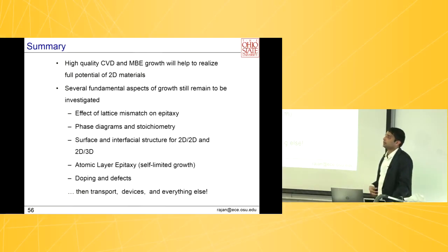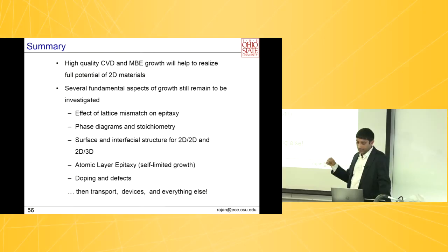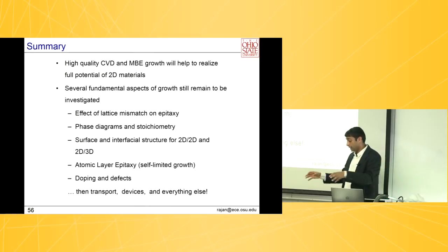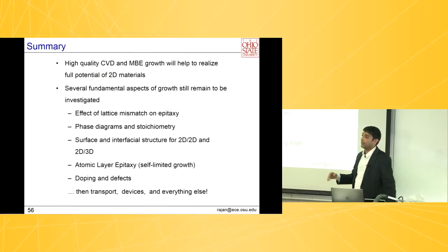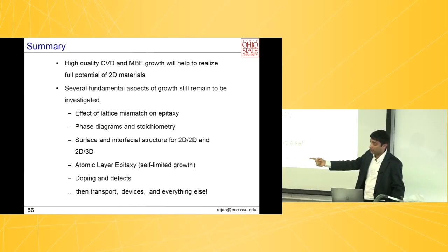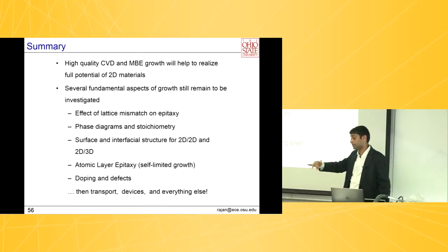What I was saying is that ex situ doping is a big advantage, if you can just deposit things on the surface and dope from the surface, like a surface donor. If that works, that's good. But then you have to come up with a compatible process next to it, because obviously you can't leave the surface open. You have to put something else on top, and the step that comes later, whether it's some passivation step or something else, may not be stable. For example, when you put potassium, if I passivate the device with silicon nitride, I don't know whether it's still going to be stable.